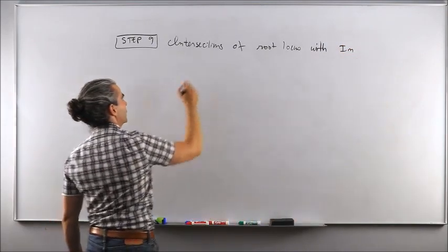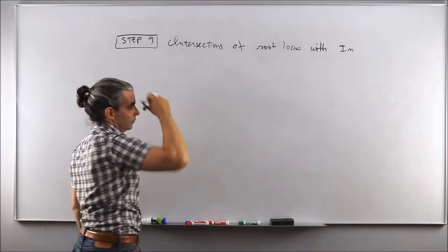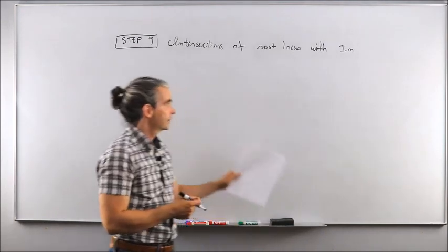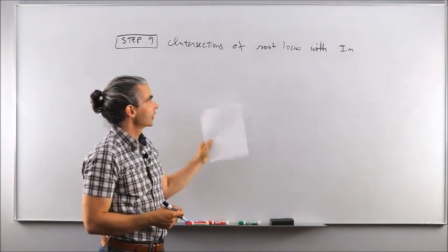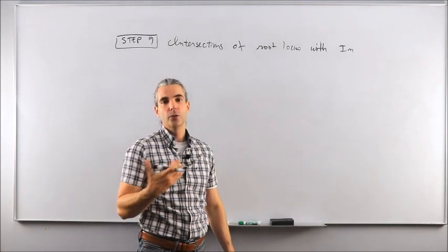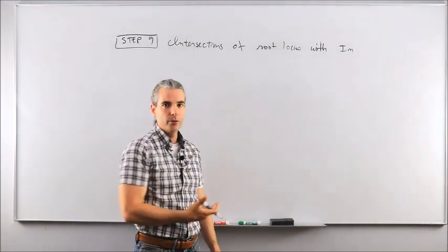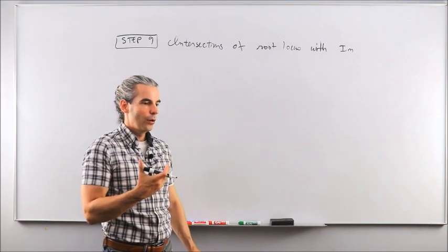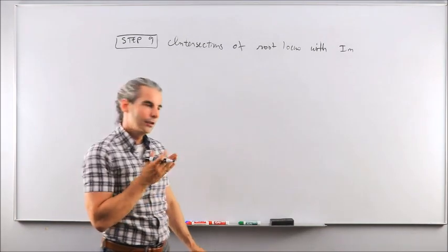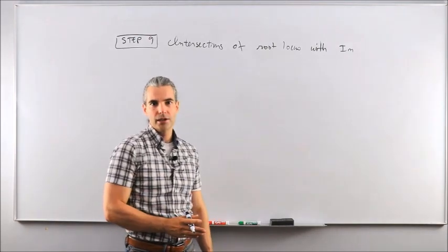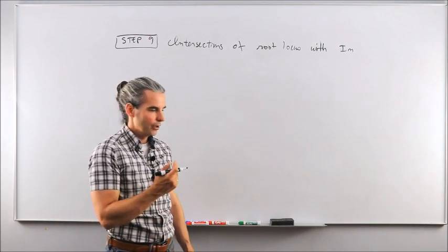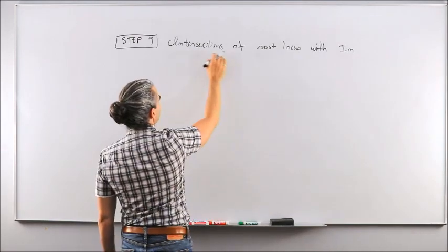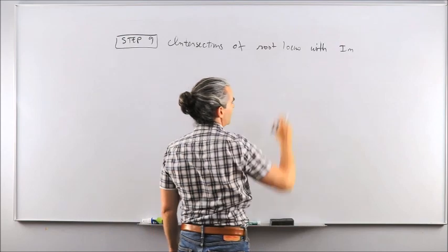Why is that an interesting thing to calculate? Well, to get a more accurate representation of the root locus, obviously, but also in this step, we should be able to figure out the value of the open loop gain, Kp in our example, or generically speaking, just K, that would make the poles transition from the left-hand side to the right-hand side of the complex plane, or vice versa. Because they're going to move from right to left or left to right at these specific intersections of the root locus with the imaginary axis.